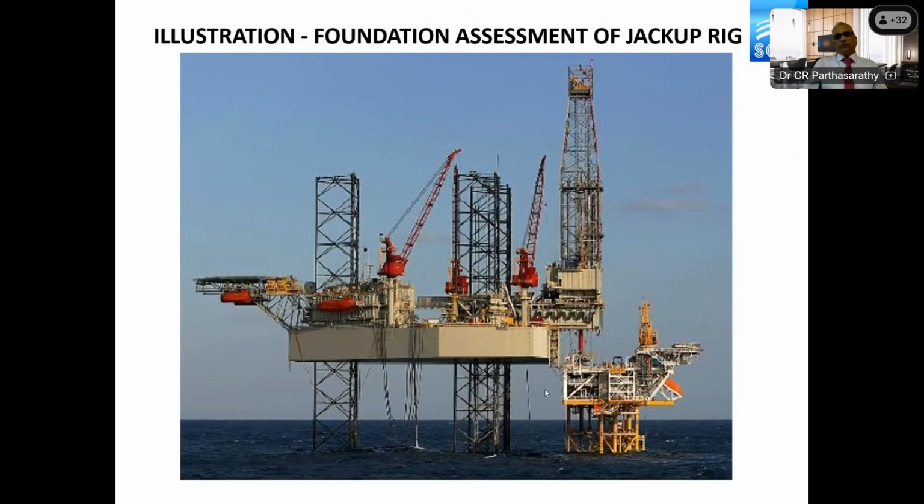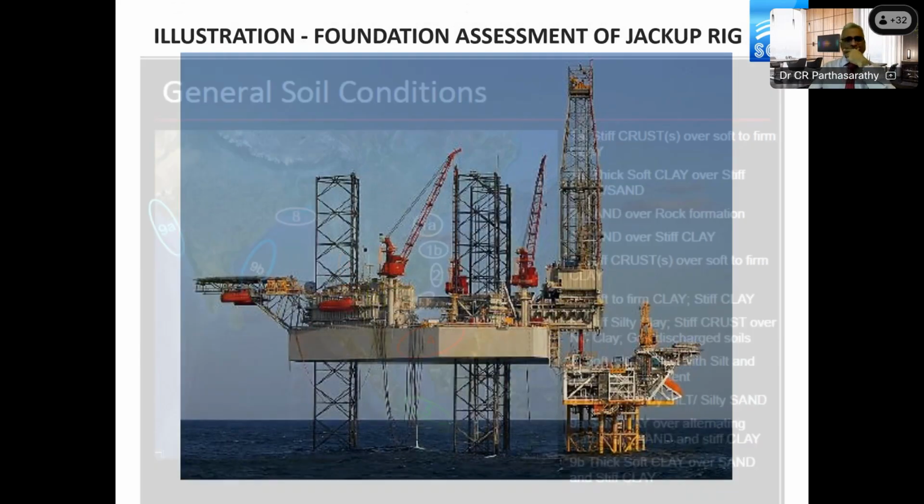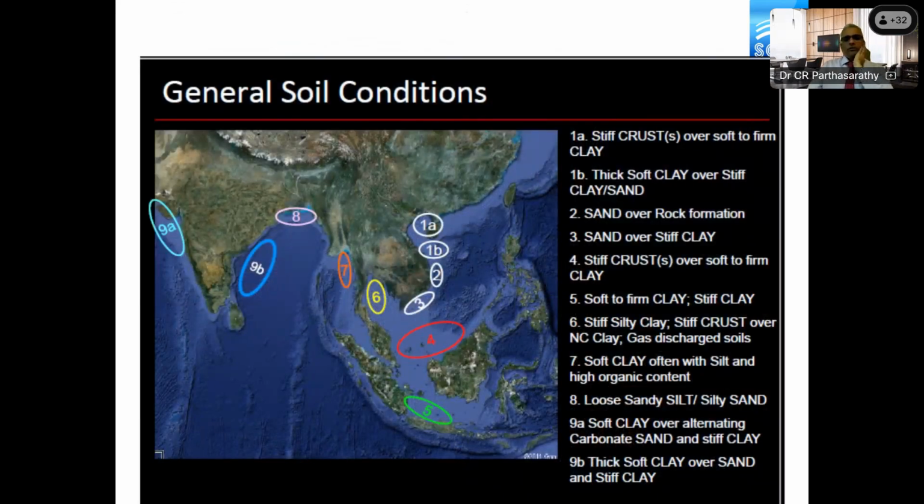Let me illustrate two or three quick examples of foundation assessment of the jackup rig. When you look at the statistics and the data across different geographies, like in Indonesia, it's all a normally consolidated profile. Thailand and Malaysia are also similar, and you have the crustal layer. The east coast of India has under-consolidated, very deep deposits of soft clays, so penetration of rigs of 30-40 meters is not uncommon. On the west coast of India you also have soft clays, with a cemented calcarenite layer, so it's a potentially variable layer.